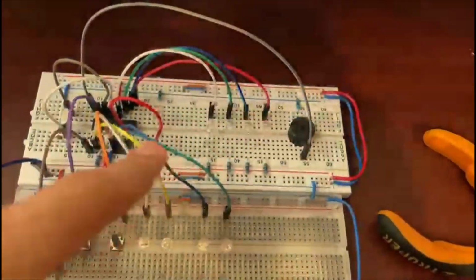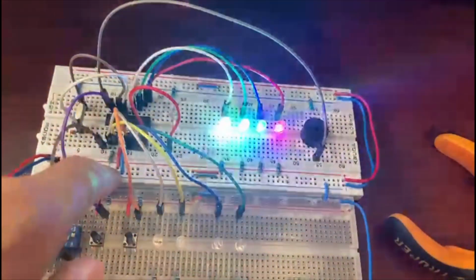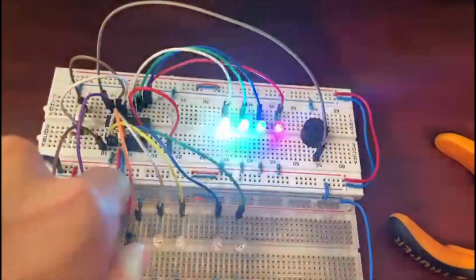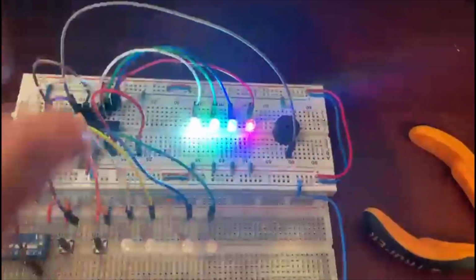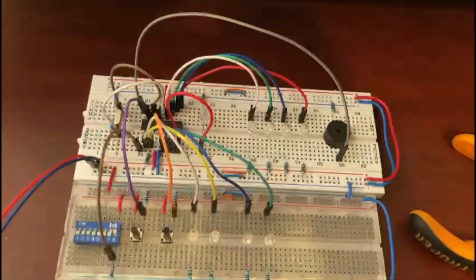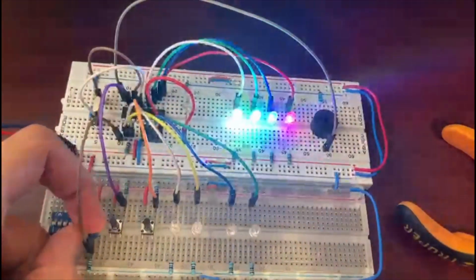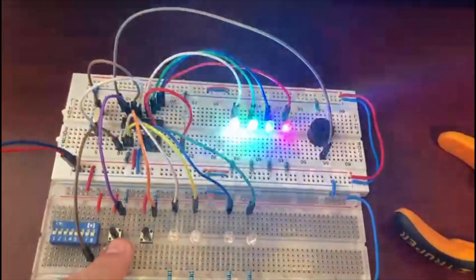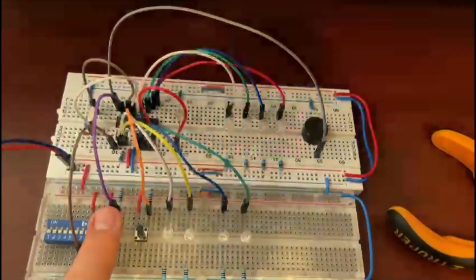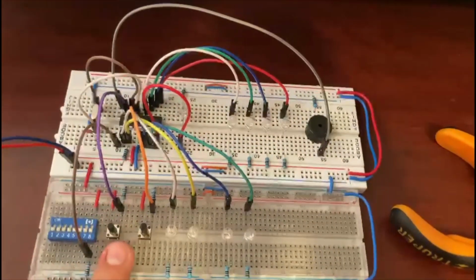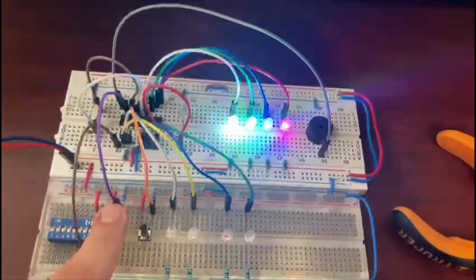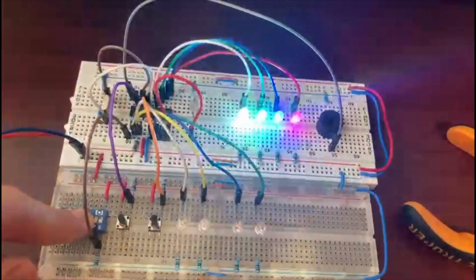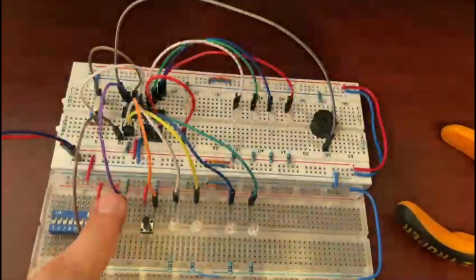This one is connected to RA4, that is also connected to a 10K resistor to VCC or 5 volts. Now we can see that we have to first open the door. We're going to see that it sends us an alarm, and it does. We press again, it sends us the alarm because the door is open. We can't start the process. We do it again.